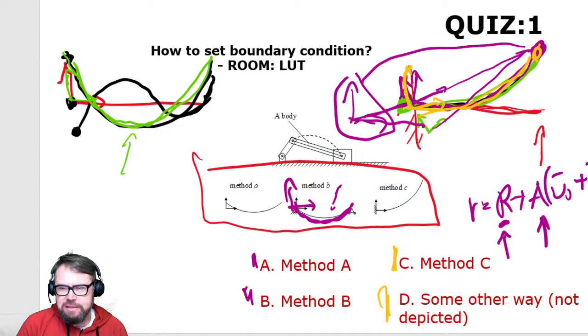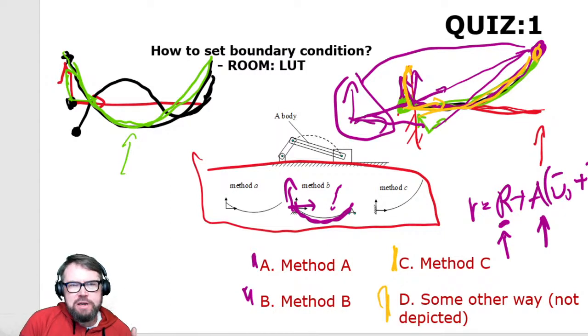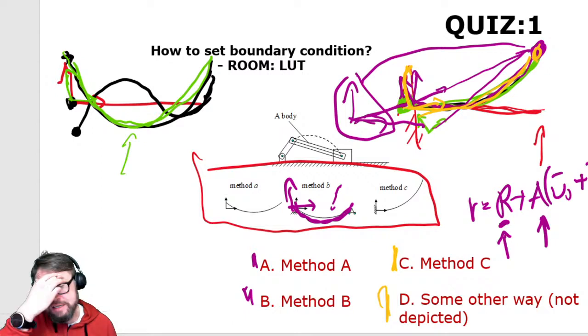And with that, okay, here's the summary. The floating frame of reference formulation, the name comes from the fact that the modes that I used in modal reduction can be obtained by using free boundary condition. And in a free boundary condition, the reference coordinate is not rigidly attached to the body, but is floating with the body, following, kind of like coming along, but not completely. I don't know what would be a good way to express that in English, but anyway, hope you got an idea.